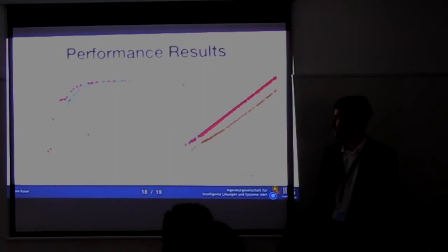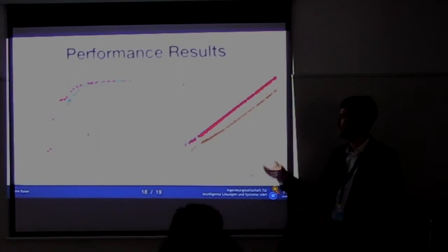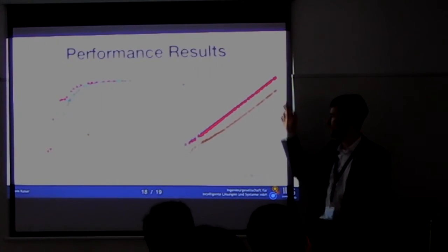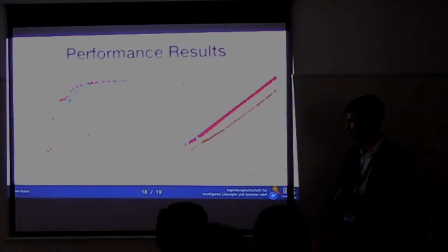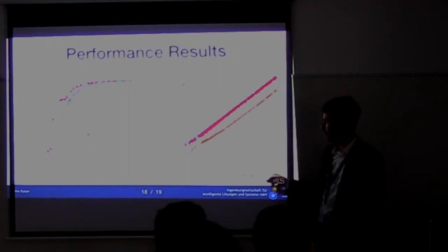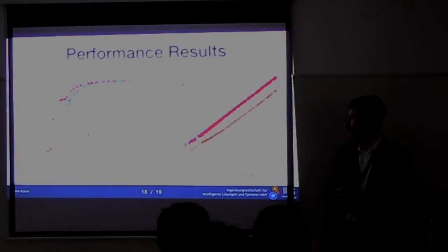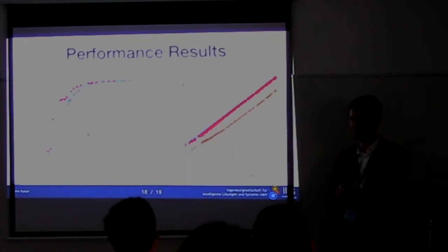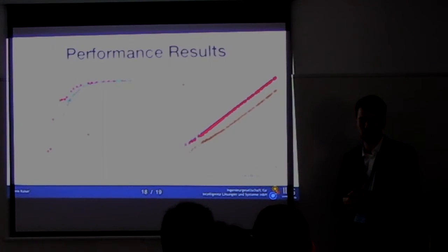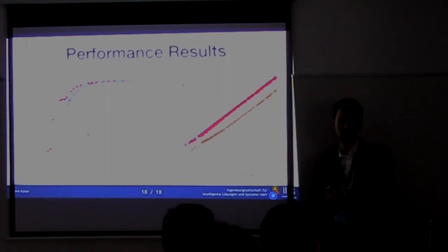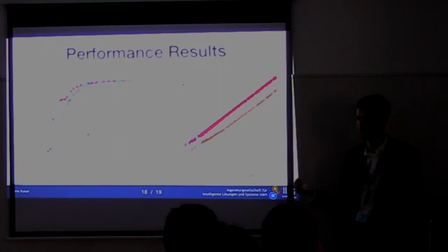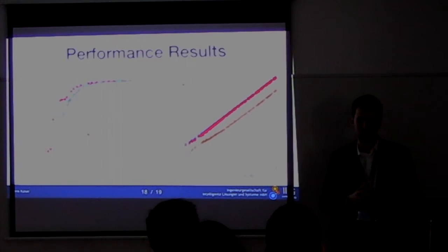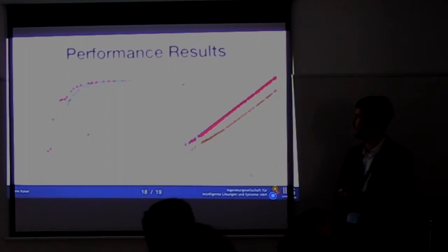And what we also measured is the time for the calculation of these central moments, and also file reading and calculation of center of gravity. Since both of these axes are logarithmical, this is still a linear dependence, at least until 1 million tetrahedrons. We didn't have files which had much more, so maybe at some point you will run into an issue with not enough memory, and then it will slow down. But in our case, this wasn't the case.